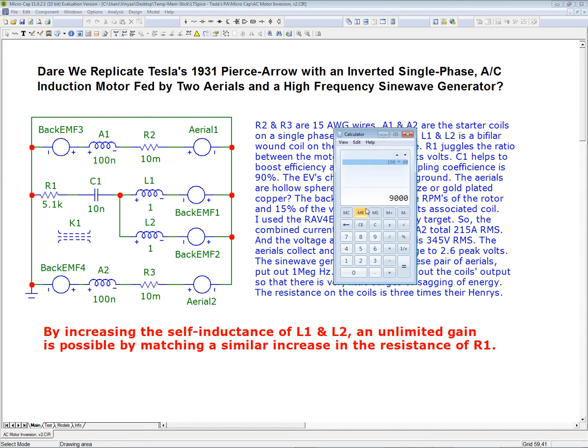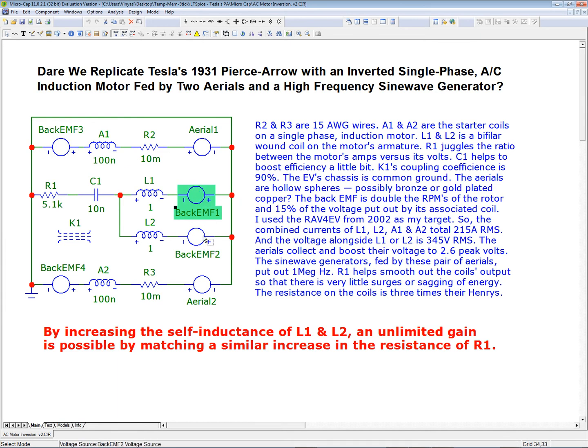So in case the motor should be under strain and rotate at 18,000, 18K RPMs, that would be 300 hertz. And that's what I put on all 4 back EMF sine wave voltage sources in the circuit simulation, turned around in reverse to everything else. And I tested it because if I turn it around the other way, they actually step up the frequency of the back EMF voltage sources, sine wave sources, and the voltage. I finally get an appreciable gain or loss depending on which way I orient them. And so I oriented them in terms of loss and then reduced them down to a realistic set of values. But I had to make them extreme to figure out their polarity in the circuit, which way they have to be turned in order to actually give me a certain amount of load to load the circuit.